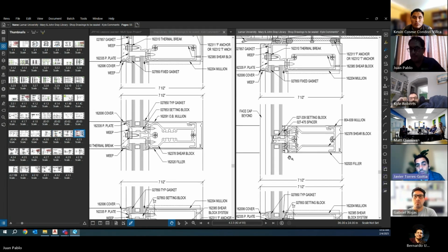Now, we do need to pay attention to how tall our wind load clips can get, because in this particular situation, since we were stacking the full height of this mullion, we were having some considerable thermal expansion movement. I think it was in the order of 1.2 inches of thermal.